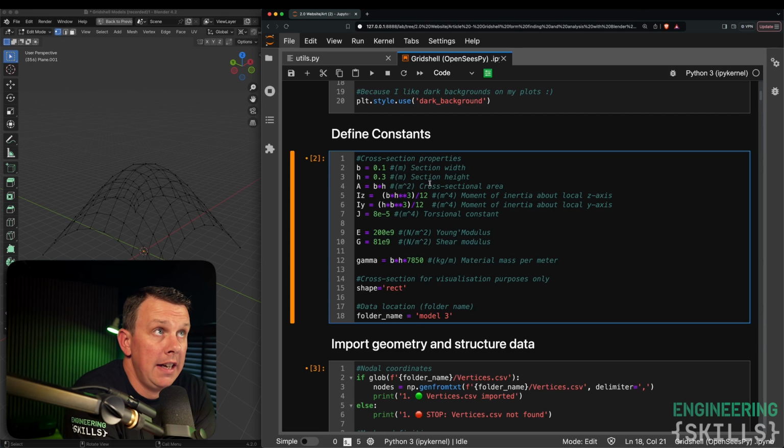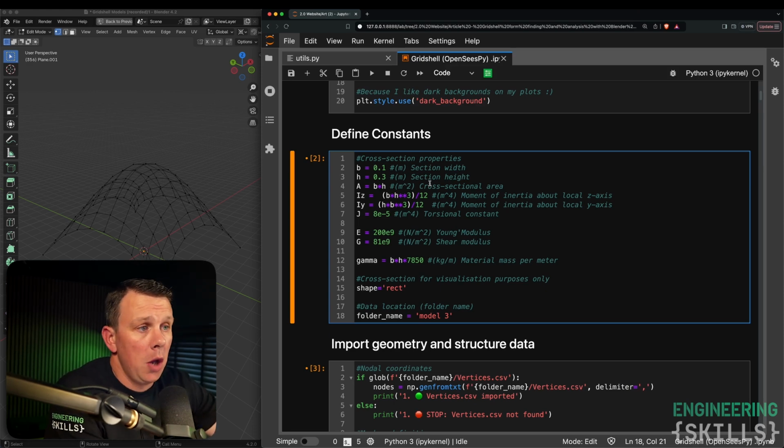And this is often analogized or compared to a ball sitting perfectly balanced on top of a hill. Any disturbance of that ball, it's an unstable equilibrium, any disturbance will cause it to roll down the hill. If you open any textbook on Euler buckling or stability analysis, you'll see this analogy. And the same thing maps onto our grid shell structure. In theory, it's in a state of equilibrium when it goes from tension to compression, but that equilibrium becomes unstable in compression, and so we have to essentially simulate the joints being locked for us to solve it using OpenSees.